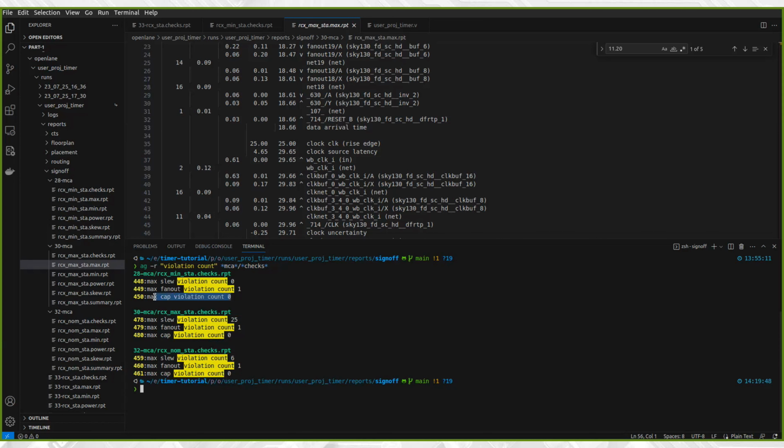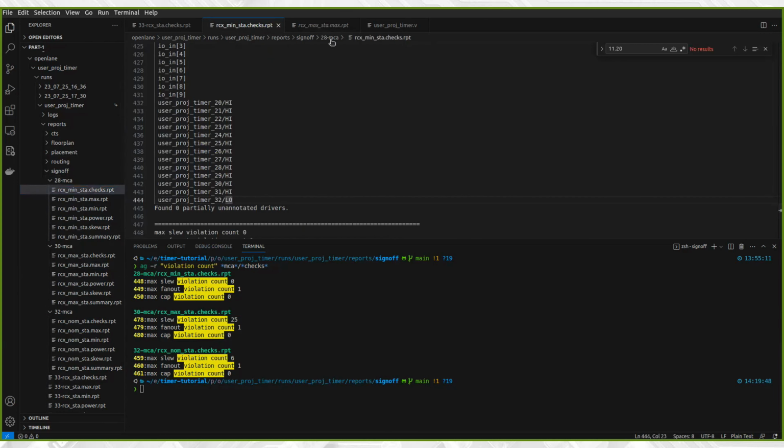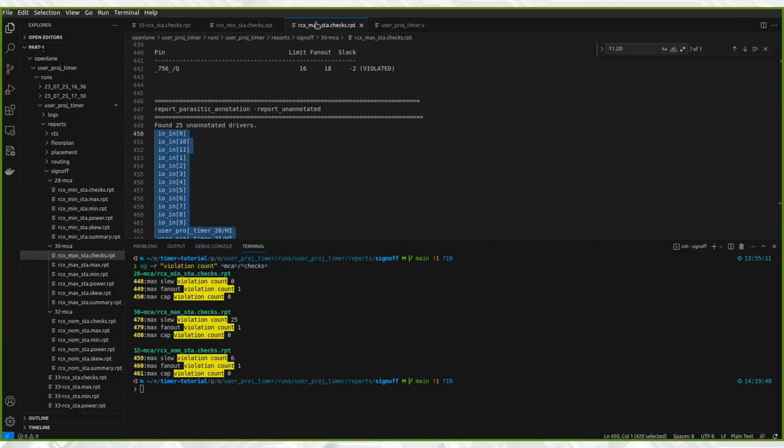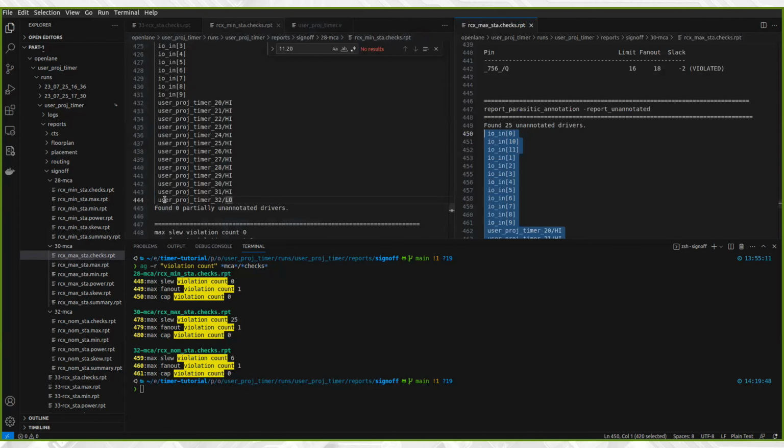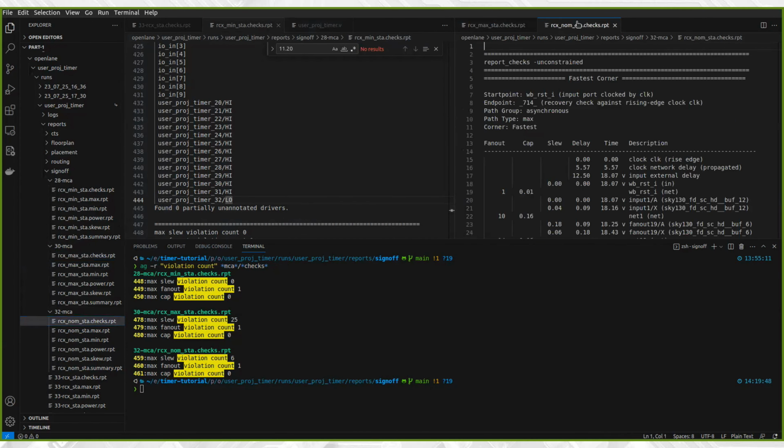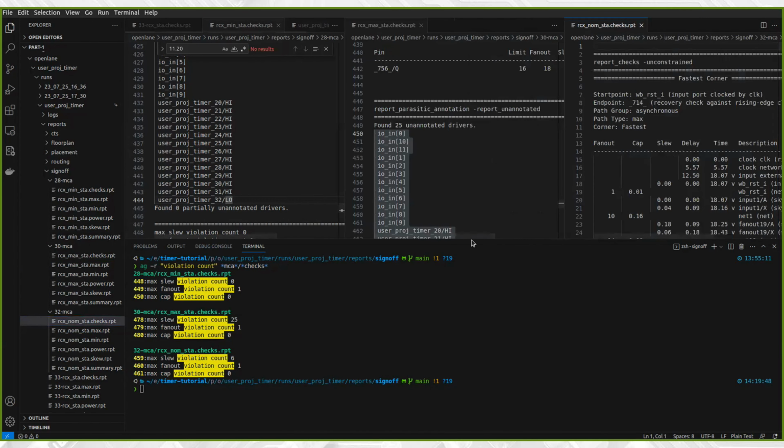For maximum transition, the constraint is set to 1 nanosecond for better implementation, or for sign-off, it should be 1.5 nanoseconds for Sky130 technology. Therefore, the reported violations are not actual violations. Moreover, the achieved maximum actual transition of 1.09 nanoseconds is great for this node.